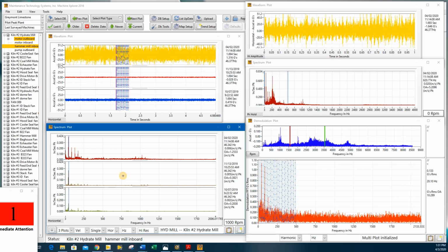And I'm going to use my left and right arrow keys and watch this number right here to pick off the highest peak. 0.13, 0.09, 0.18, 0.14. And we're going to get that number all the way to 0.4 if we can find the right frequency. So I'm just using the left arrow key to move it down. I started on the high side, so I'm just moving it left. As you can see, that defect frequency we're interested in is around 42 hertz.